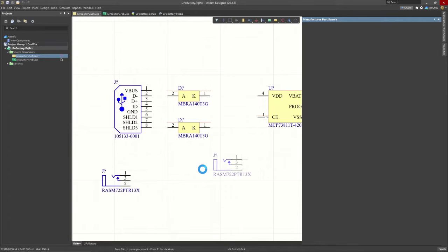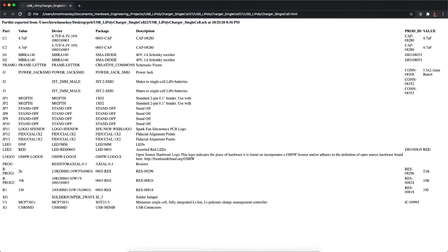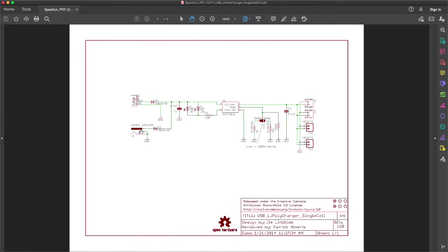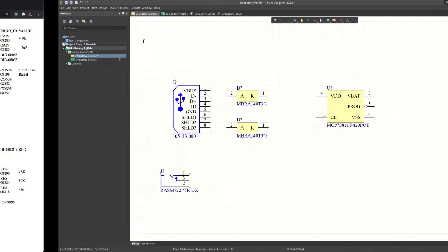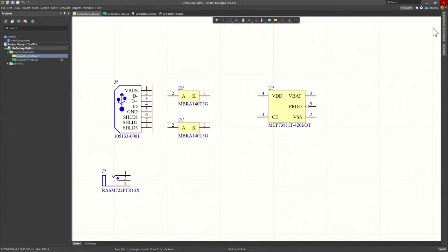What else do we need to place? We have the J1, the diodes, the capacitor, 4.7 microfarad capacitor. For the capacitor, we need to know the voltage that it can handle. 6.3 volts is what they use. And that depends on the expected input voltage range. You can choose whatever capacitor you want depending on the input you're expecting, but this is a generic 4.7 microfarad capacitor.